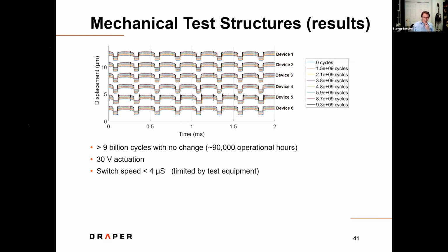Gotcha. Actually, maybe more than that, now I think about it. I think with a 1 dB tolerance, it's probably more in the 30 range. And then I think you can get almost to 100 if you're willing to go to like 3 dB loss. Sorry, I don't have the exact number off the top of my head, but it's relatively broad, right? It's not like you can cover decades of bandwidth, but compared to other methods, it's fairly broad. Sure.